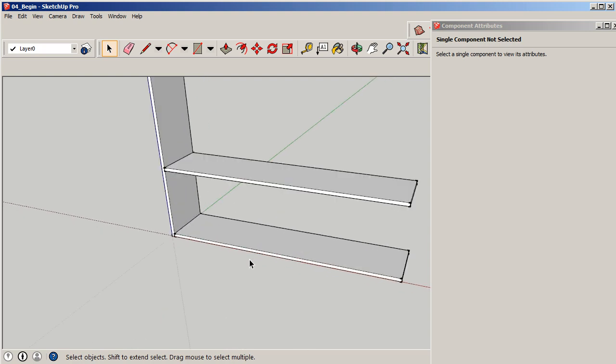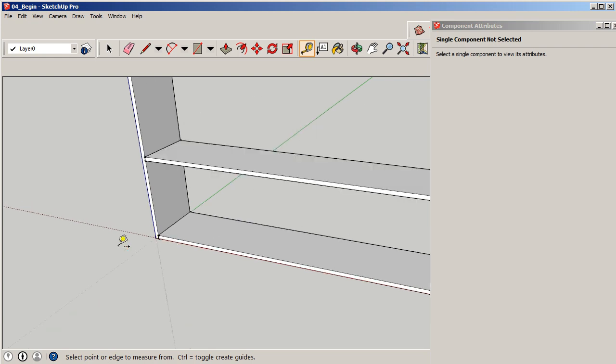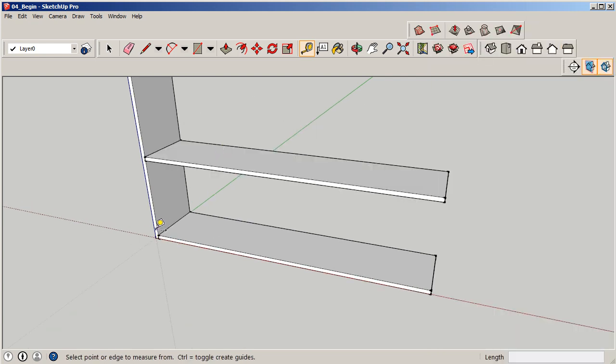So now grab your measurement tool. This measurement should be 3/4 of an inch shy of 5 feet. So let's close this window, and we're going to go from this corner to this corner. It should be 4 feet 11 1/4 exactly. So the other side is actually going to have a thickness, which is right there, so we can go ahead and place that.